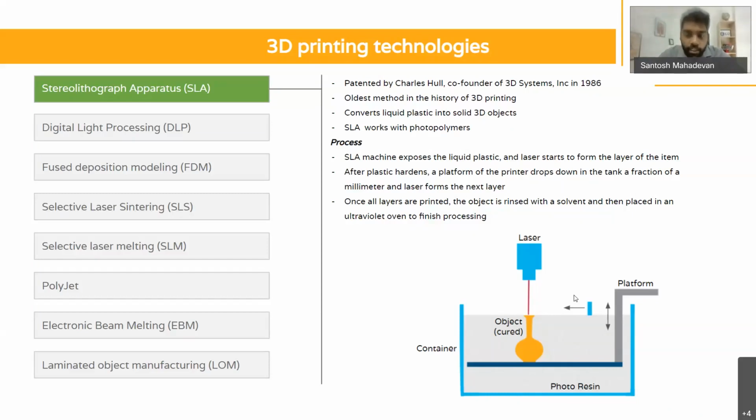To give you clarity, if I were to make a 25 mm by 25 mm by 25 mm cube, I will say that each layer is going to be 1 mm in height, meaning I will have 25 squares which measure 25 by length and 25 by width, and I will stack 25 of these squares one on top of the other to get the 25 by 25 by 25 mm cube. So this is the basis of deciding dimensions for your 3D printed part.